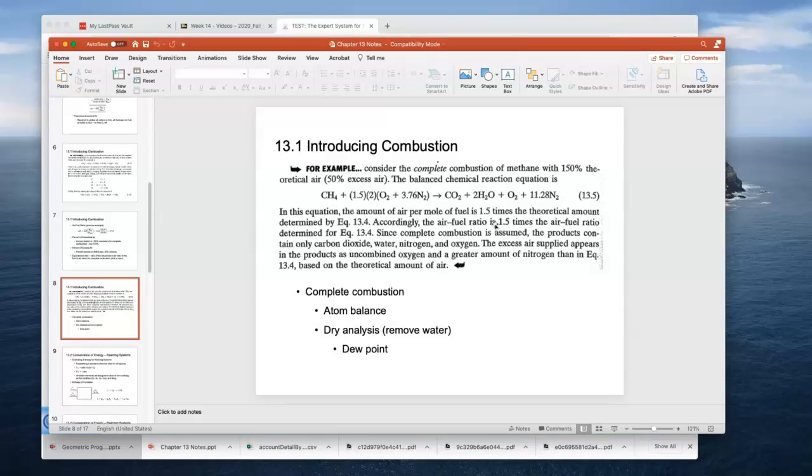The difference is, when we talk about the adiabatic flame temperature, if I came in with these components and as they transition to these components, no heat was lost from the combustion chamber and all the heat stayed in, that heat would cause all of these components to rise in temperature.